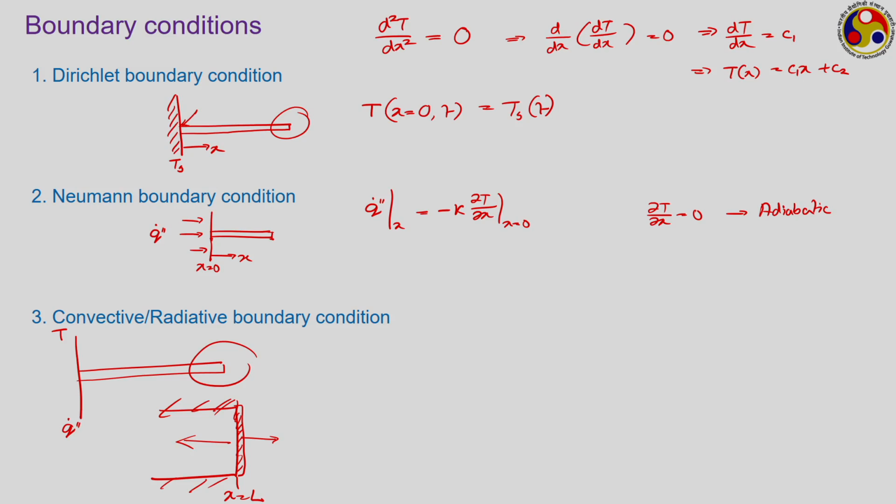That is, whatever conduction heat flux you have on the left hand side, which can be written as minus k dou T dou x at x equal to L minus, where we put the minus to indicate the left hand side, that should be equal to the convective heat flux acting on the right hand side. And how do we write the convective heat flux? That can be written as h into T at x equal to L plus minus T of the surrounding.